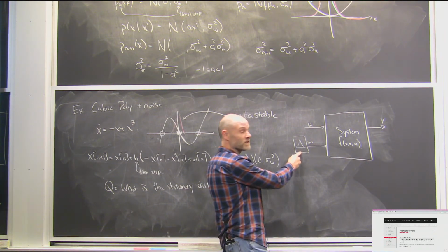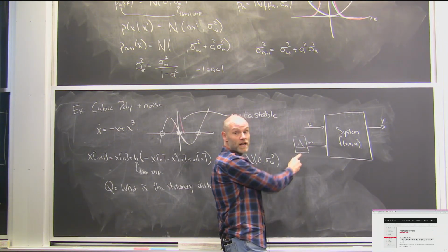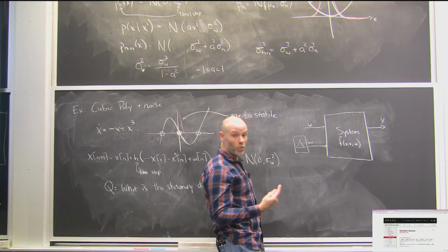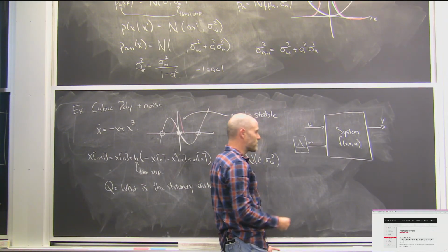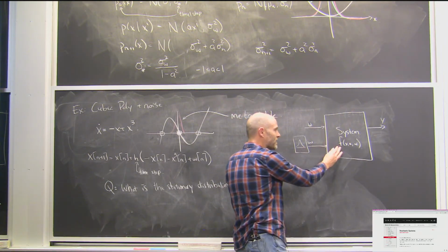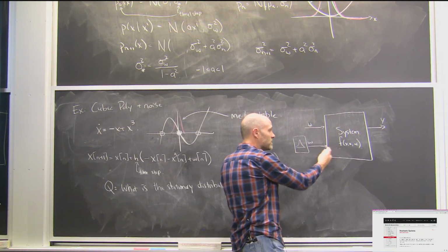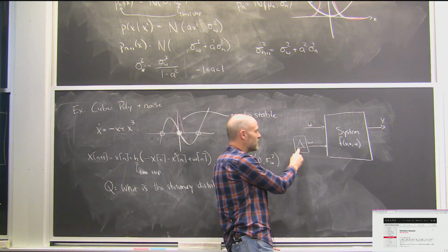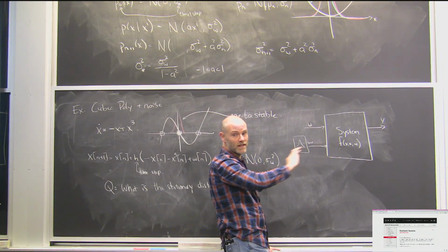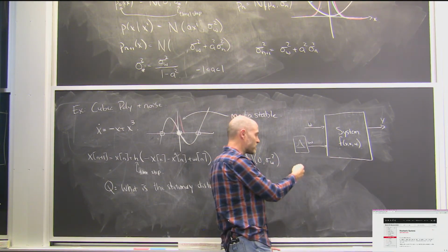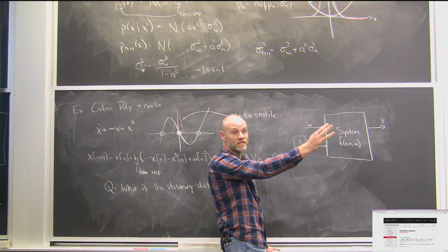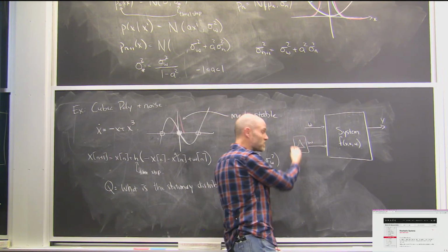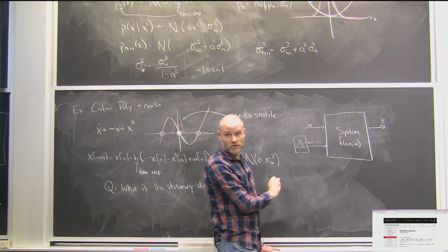And so we've done that carefully a few times in this sort of random noise block. And then it'll be right every time you do it. But it's actually way better than that. It's way more important than that, right? So by taking that decision, it's very easy to get repeatable simulations. If I want to set the random number generator that defines this, even if I'm simulating a random, huge complicated diagram, if I just lock in the random seed, then I get a deterministic play, I can play the same random thing twice. So there's choices around that, and you can play the deterministic thing if you want.